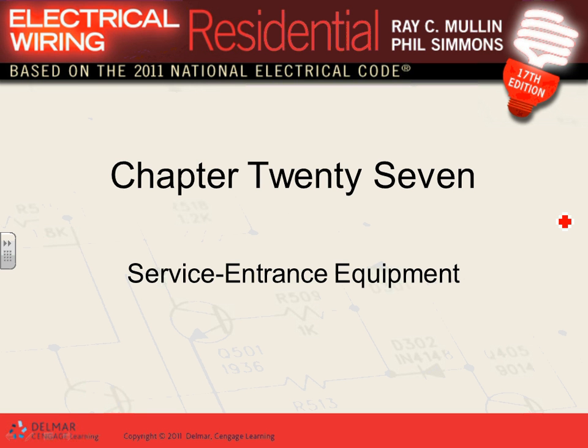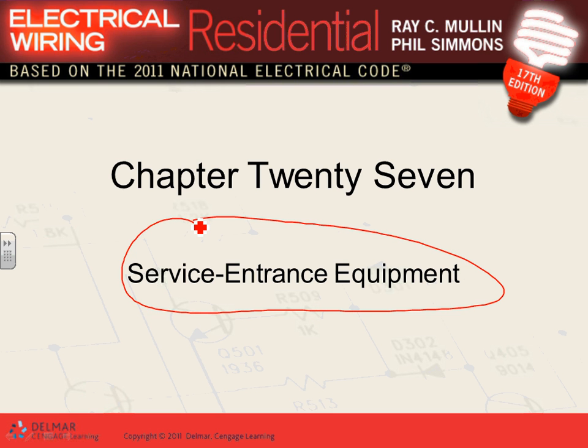When you bring that chunk of power from Xcel into your building, the first interface between you and the utilities is called service entrance equipment. That's the first panel, not this panel. The first panel that you have, where you land the conductors that you bring from the electrical utilities, is called service entrance equipment. So it's so important, guys, to understand the so-called service entrance equipment. So that's what we're going to talk about today.